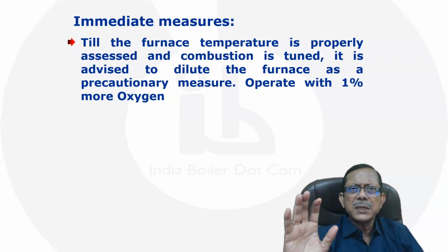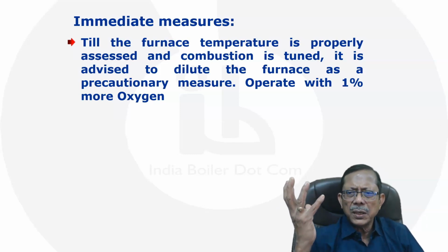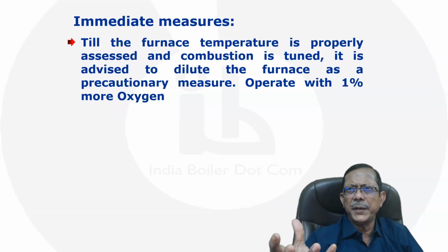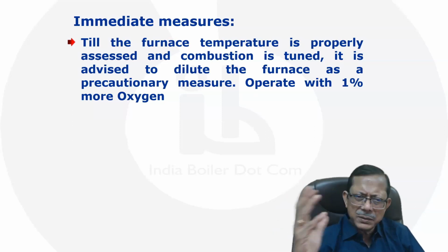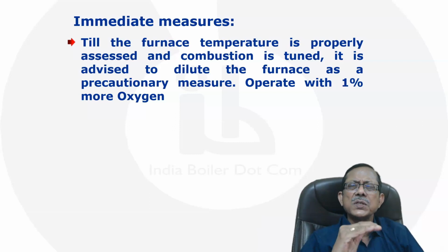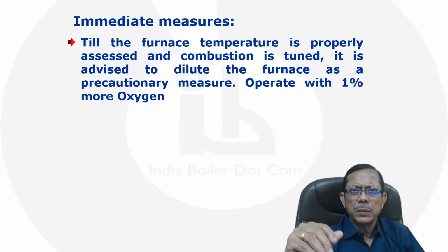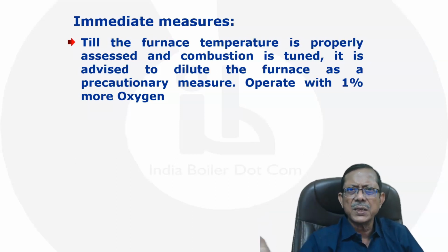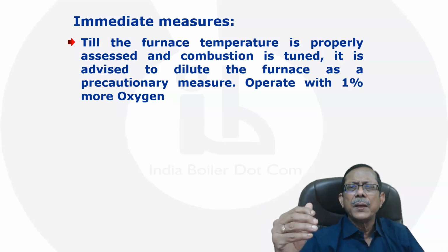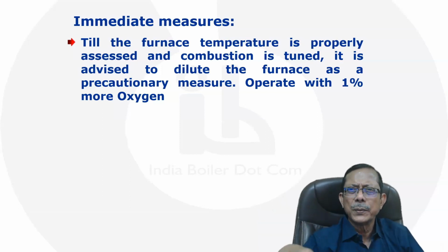So I asked them that they have to assess the total design capability of that boiler by some test, some trial, and find out what load the boiler is capable of handling without disturbing the tube metal temperature, the flame condition and the furnace condition. So till that time, one logical suggestion is to keep the furnace cool.